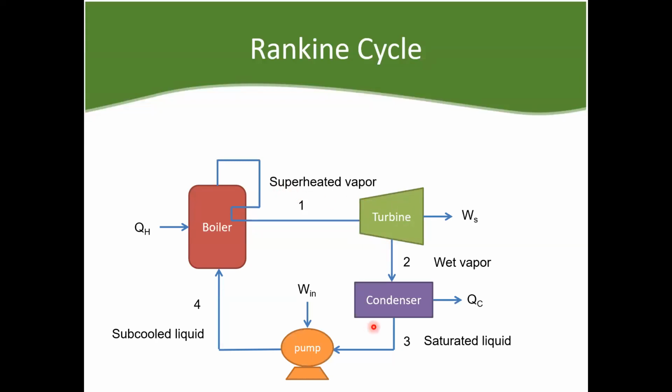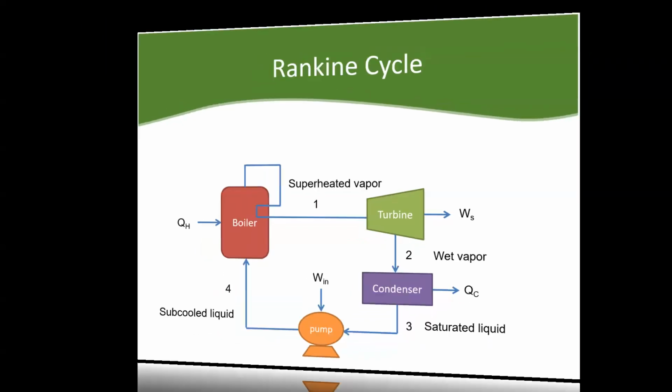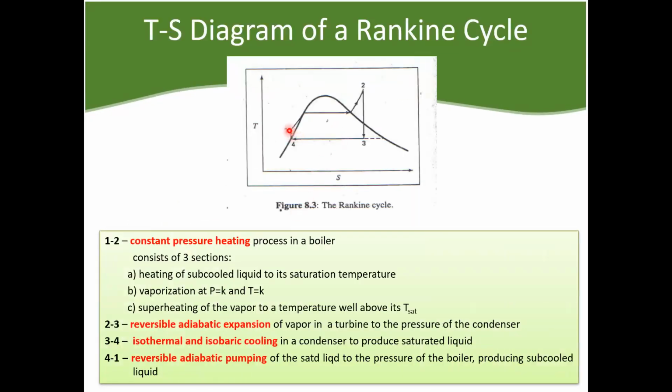And in the condenser, it releases the fluid as a saturated liquid. Now, since it is now liquid, the pump can handle it. And there's even subcooling. Subcooling means, in our diagram, in the pump, it now exits the saturation curve. This is a subcooled region. Remember, this is the superheated region.